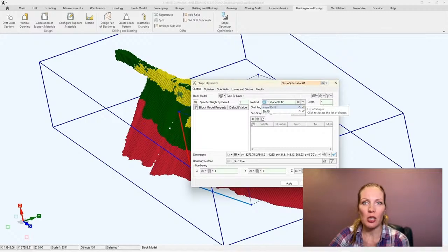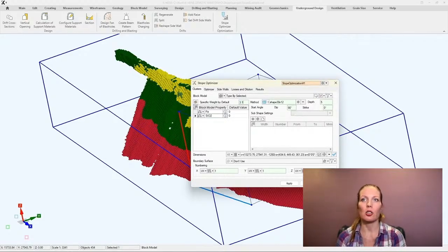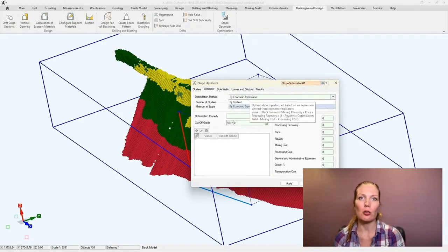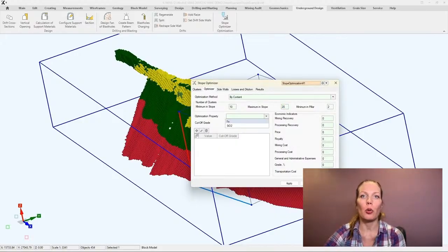After choosing the objective, constraints are applied to the clusters in sequence. This is the heart of the process. So we start with geometric constraints. The stope must fit in the allowed height range, stay within the maximum width, and avoid shapes that create impractical tapers or bottlenecks.